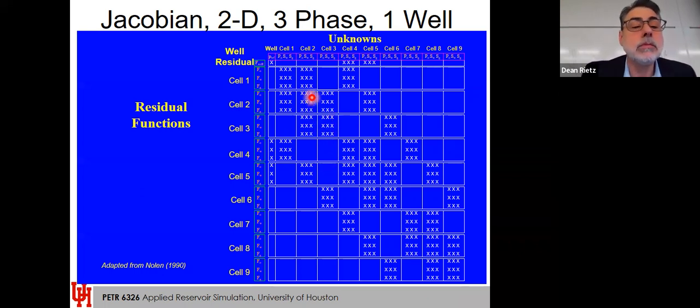So yeah, we're solving for pressure and saturation for each phase. Yeah, all 3. This is a 2D model, 3-phase, with 1 well connected. The 1 well is completed in 2 different grid blocks. No, 3 equations. Each of these are coefficients in the equation. We're solving for pressure, saturation, and saturation. So there are 3 equations and 3 unknowns.